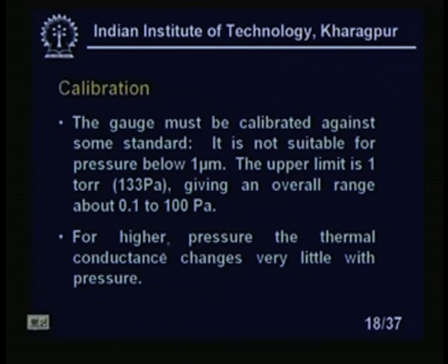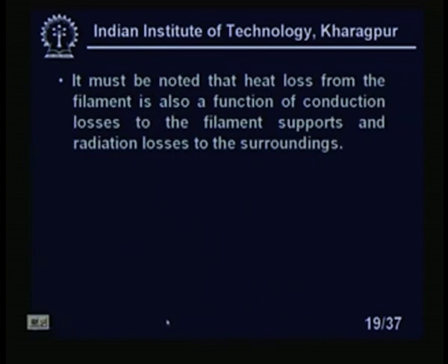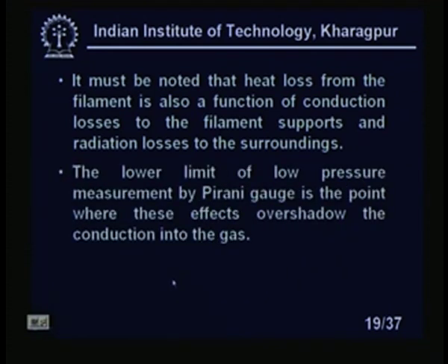For higher pressures, the thermal conductance changes very little with the pressure. It must be noted that the heat loss from the filament is also a function of the conduction losses to the filament supports and radiation losses to the surroundings. The lower limit of the low pressure measurement by Pirani gauge is the point where these effects overshadow the conduction into the gas.